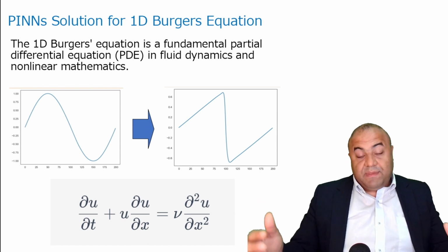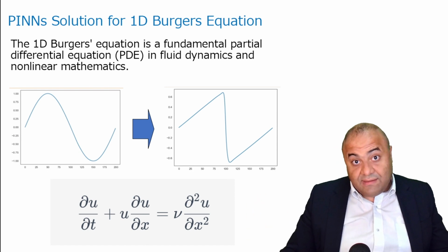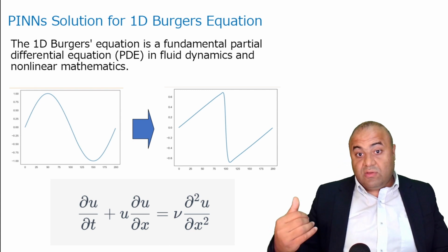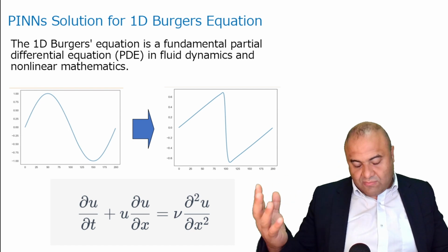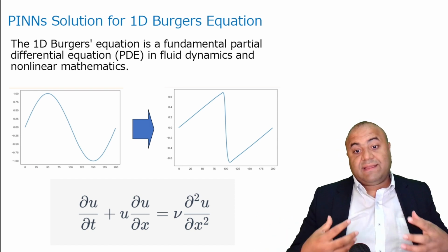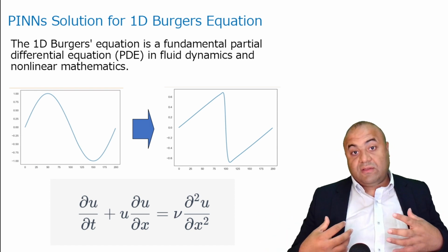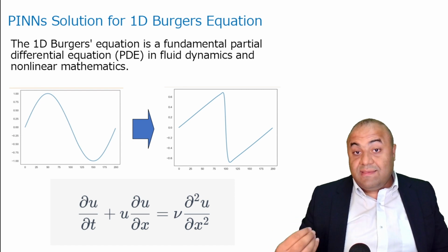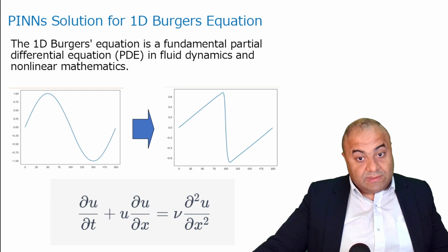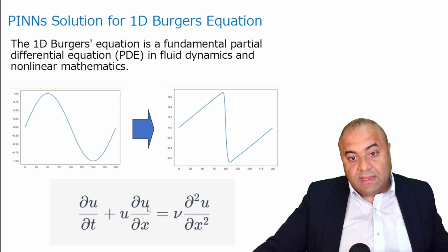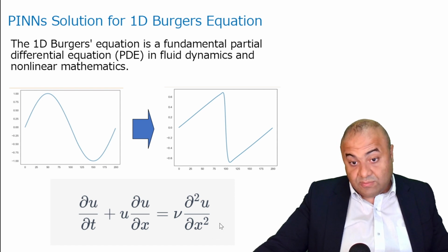Now we become familiar with finite difference methods and how to solve problems with them. We step it up. Now we have to work with PINNs, but of course we have to work cautiously. So we will start by solving the 1D Burgers' equation. Because why Burgers'? Well, first, 1D is, of course, easier, and 1D Burgers' has many things we need to learn.